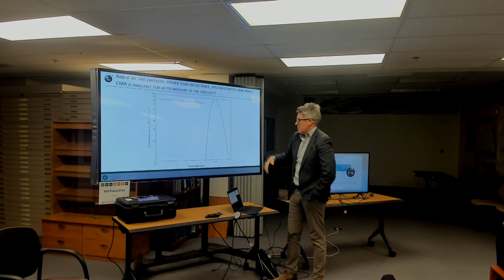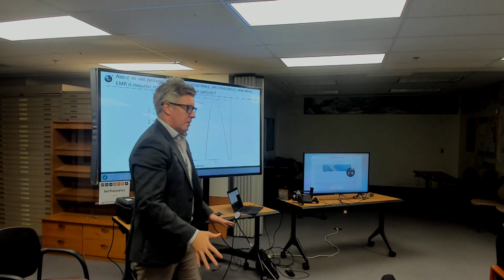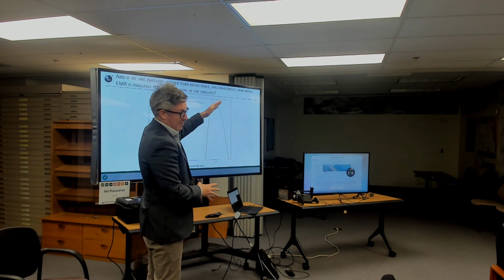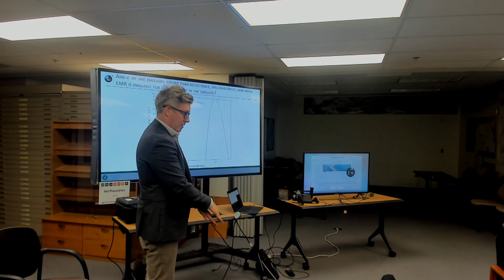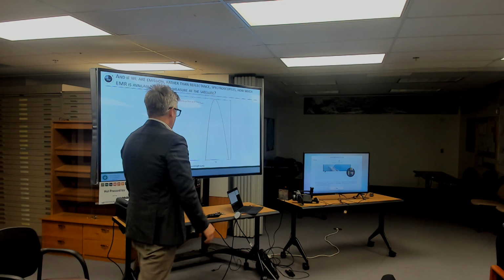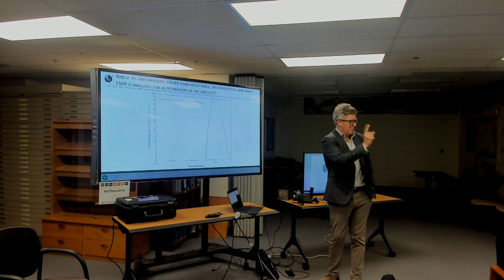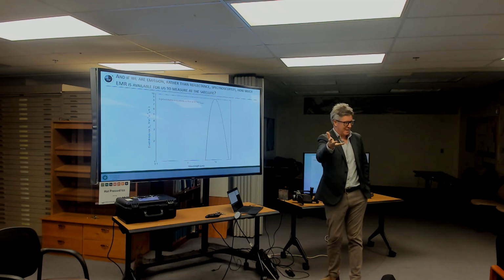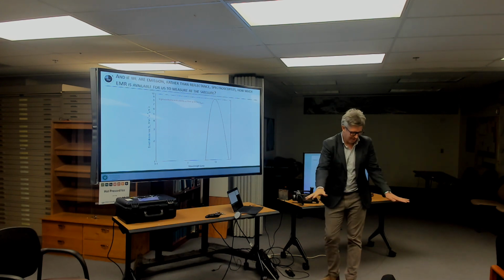Okay. So if we imagine, again, remember, sunlight isn't shining on the Earth; the Earth itself is the source. When we were doing reflectance remote sensing, the first step was how much energy comes from the sun, how much makes it to the top of the Earth's atmosphere, how much makes it down to the surface. Here, that's where we start, at the surface. It gets back to the point that you just raised about the radiation temperature, brightness temperature being different than the kinetic temperature. Is this the amount of energy which arrives at the satellite? This is the amount of energy that leaves a patch of dirt on the Earth's surface.